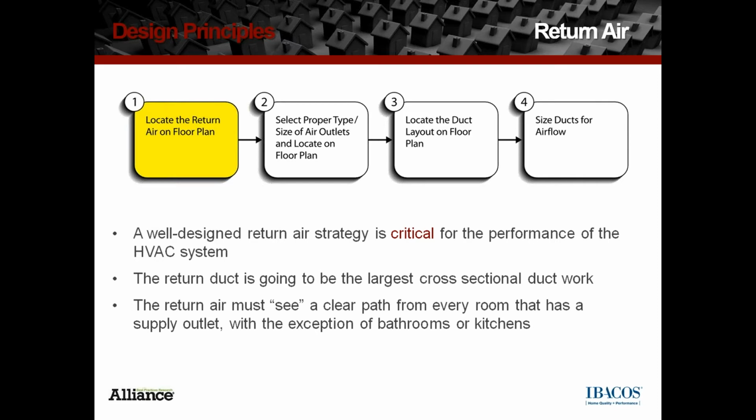You want return air to, in quotes, see a clear path from every room that has a supply outlet back to the equipment. The exceptions for return air would be bathrooms and kitchens, and that's due to moisture and odor issues. Quick question on this one.